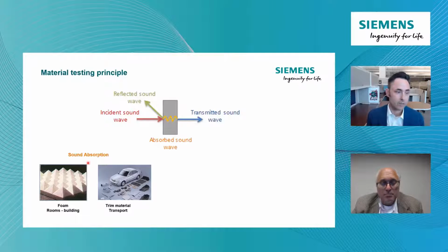Okay, so this will typically be open-celled foams, carpets. If you think about an automotive example, it's the headliner or the carpet. It's got a lot of surface area, a lot of opportunity for that sound wave, those air molecules to come into the material, interact with that material, and then sort of break apart and cause friction.